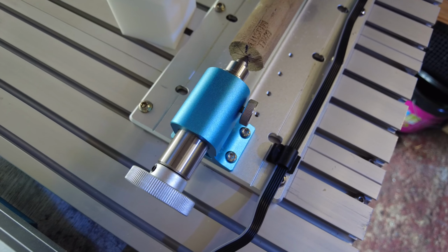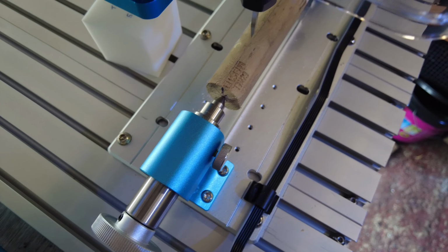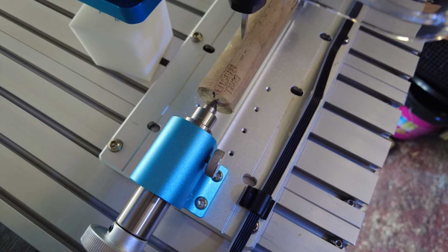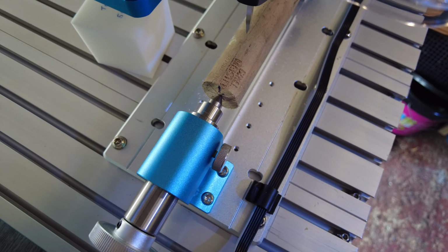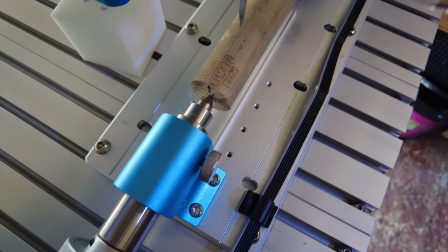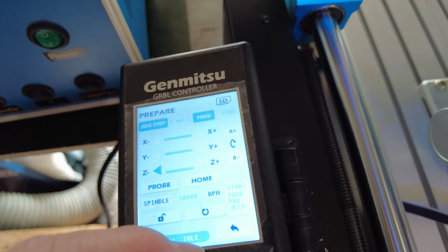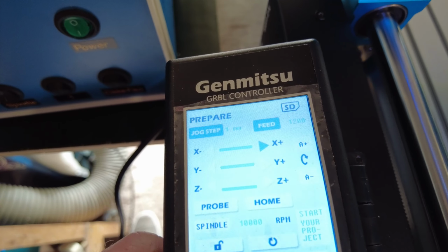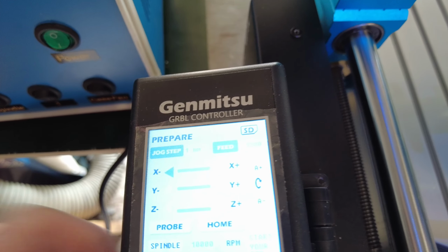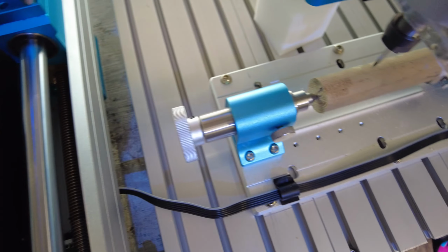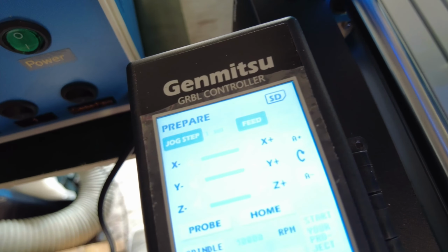And I've got a centre line there, as you can see. So that's now in the centre of the piece of timber that I'm going to actually engrave on. Okay, right. Next one I set is the x-axis. So the x-axis, I want this side, so it's minus again. So press that. Now obviously if I press that, it'll only do millimetre slots, so you go back here,